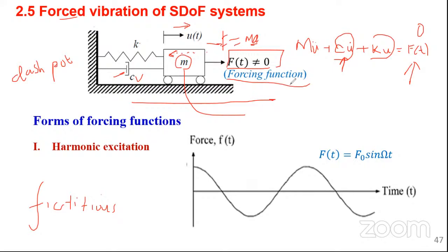The earthquake loading, of course, we have data collected over time, but it's just prediction. You cannot use a mathematical equation to accurately represent the load that will be experienced at a certain time in the future. But in the case of deterministic loads, the ones that can be determined, you can approximate them using a mathematical function.